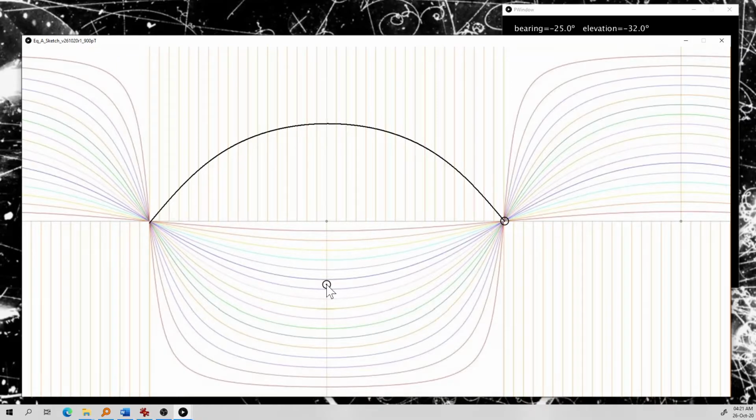So I press M to choose a point, and I pass a line, and it has the same vanishing point here that I have set. And so I press N here and M here to choose my two probe points, and I pass another line that will vanish necessarily also at this vanishing point. So we have two lines in space that we know are parallel because they have the same vanishing point. And because they're parallel, this could define, let's say, a wall going from somewhere on my right to somewhere on my left.